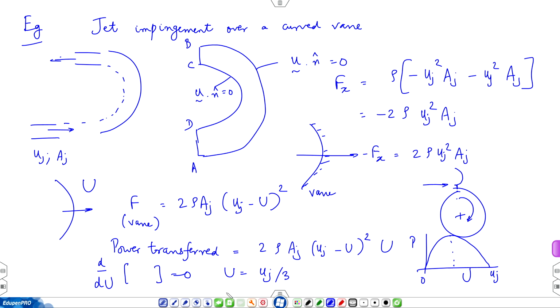But then this result is for a single vane, and we also saw that immediately afterwards its position has changed. So, you can think of a limiting situation where you have a very large number of such vanes. That is how a turbine anyway is designed. You do not have a single bucket or a vane, because soon it is gone from that position. So, you will have another which will take its place. In a typical hydraulic turbine, you will have many such vanes.